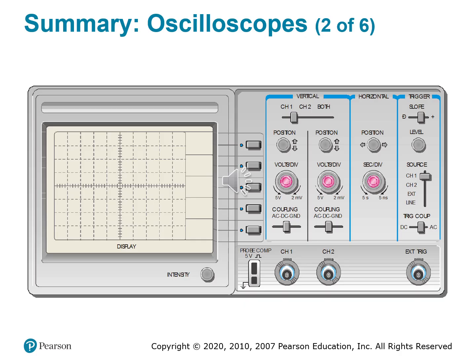The level sets the voltage threshold for the trigger. The source helps you choose which channel or external input to use for triggering. And then the coupling, AC-DC, that filters the trigger input signal. What else? Yeah, so if you have a proper trigger, it locks the waveform in place, and that makes it readable and